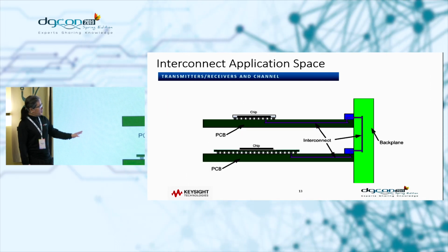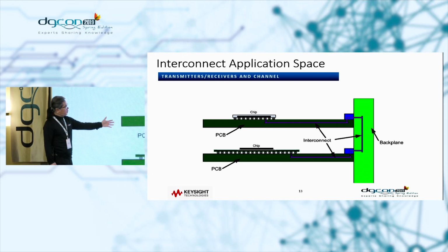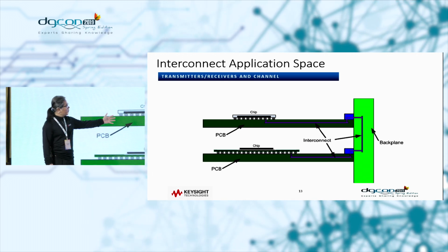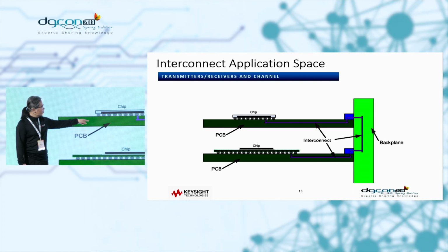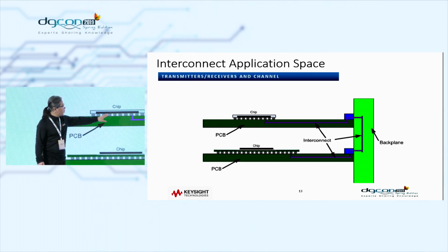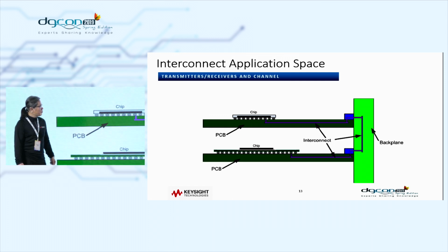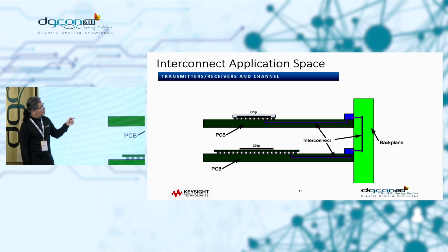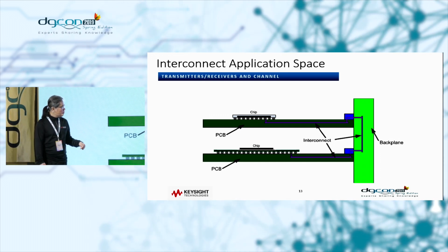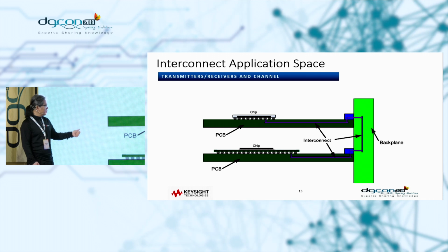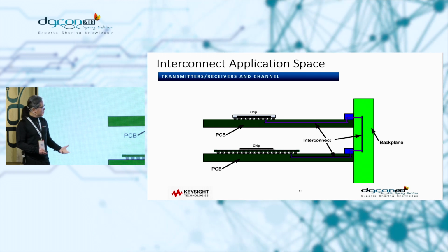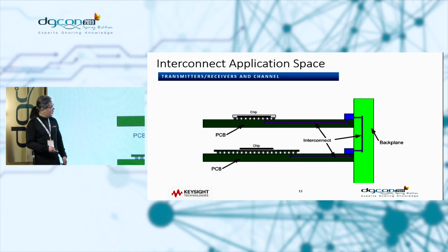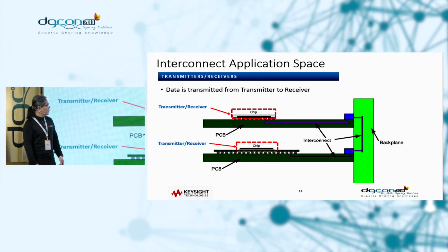So let's take a look at one simple one. Here you basically have a chip, and then from the chip you have a via, solder balls, and then going down to the board level through the via structure, and there are transmission lines and another via and connector, going through the backplane, and then coming back to this, right? This is a typical entire interconnect for the design.